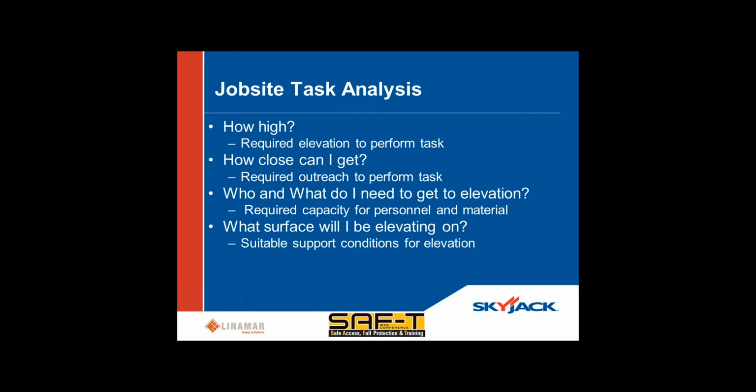What surface will you be elevating on, right? You need to have suitable support conditions for that elevation, not only from a perspective of whether they're level or flat, but whether they're actually capable of bearing the weight or pressures of the particular lift that you're going to support. So you certainly have to know something about the ground conditions that you're looking to elevate on. And how are you going to get the lift to the task, right? In some cases, you may not have any obstacles between you and your task. It may be relatively straightforward. In other cases, you may have rough terrain or other obstacles in your way that you have to consider in how you're going to get your lift there.